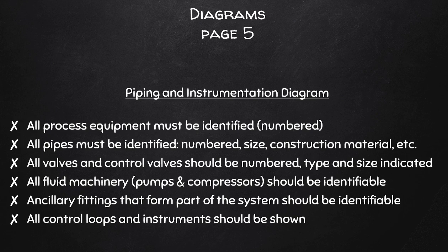Another thing to consider is the pipes that you are labeling. All pipes should be labeled for a pipe and instrumentation diagram. You provide the sizes, nominal diameters, and materials of construction. If it's stainless steel, then it would be SS 304, and so on.